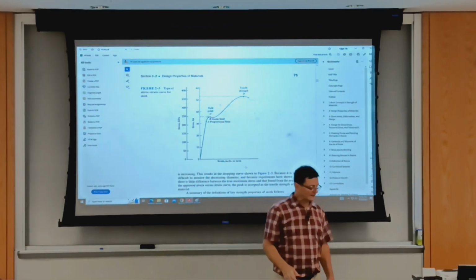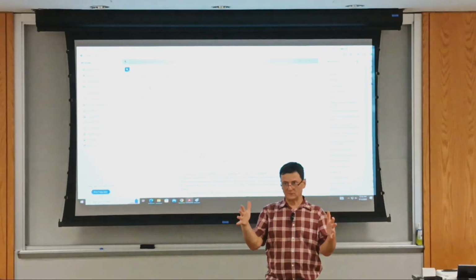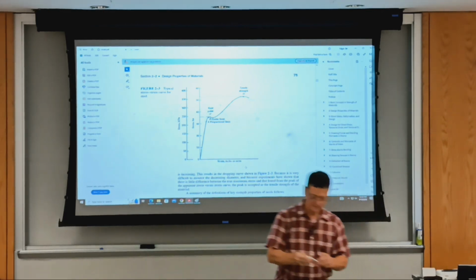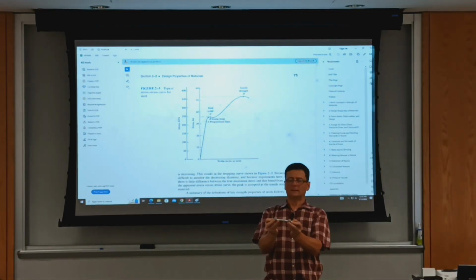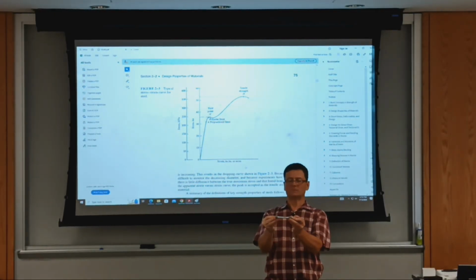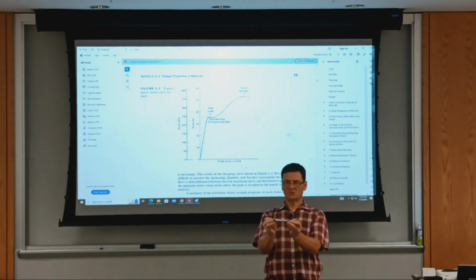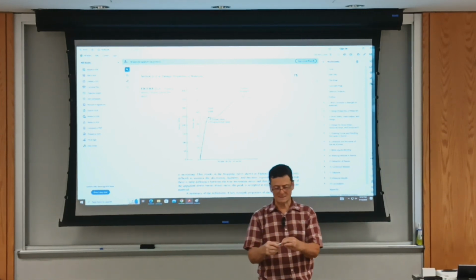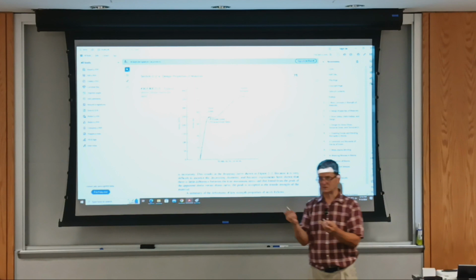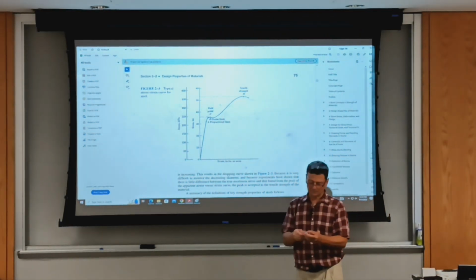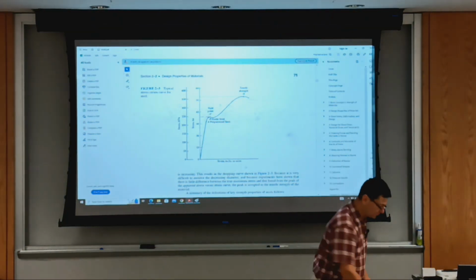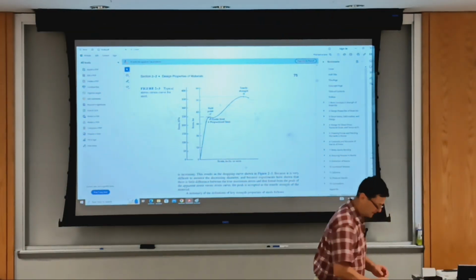You can take the two specimens that I have here, put them end to end, like right before they separate, measure the final length, subtract the initial length, and calculate the strain as a percentage. If this is more than 5%, the material is accepted as being ductile. Anything below is assumed brittle behavior.